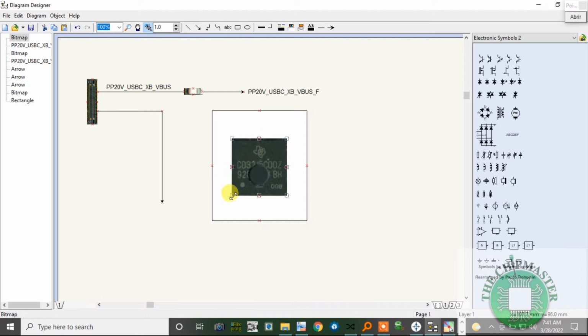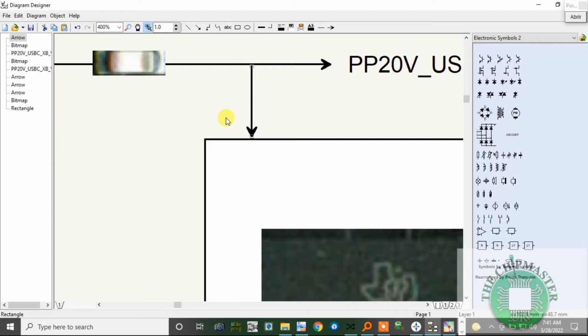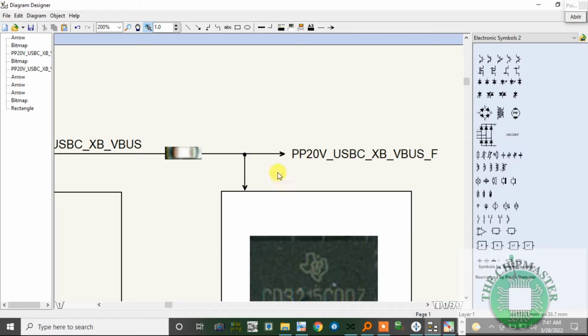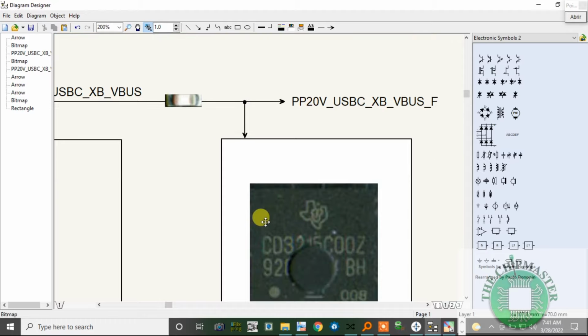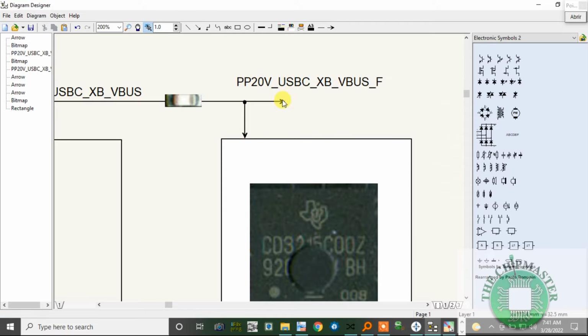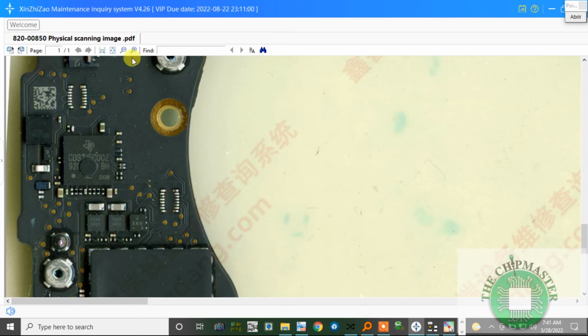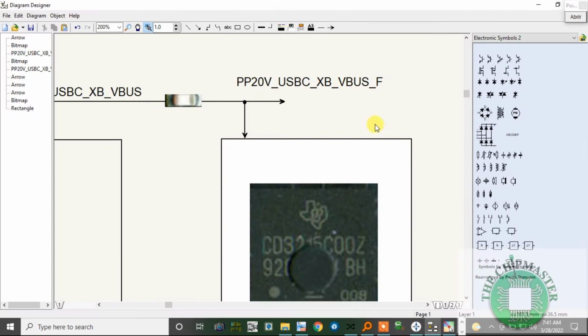Alright, this is our USB-C chip, logic power delivery chip, communication chip, or we can call it the CC configuration protocol chip, and that's going to go here. Right, let's put a dot there. Good. Alright, so the 5 volts coming in is going to control the gate of our MOSFET, which is Q3200. I'm just going to draw 2 MOSFETs.